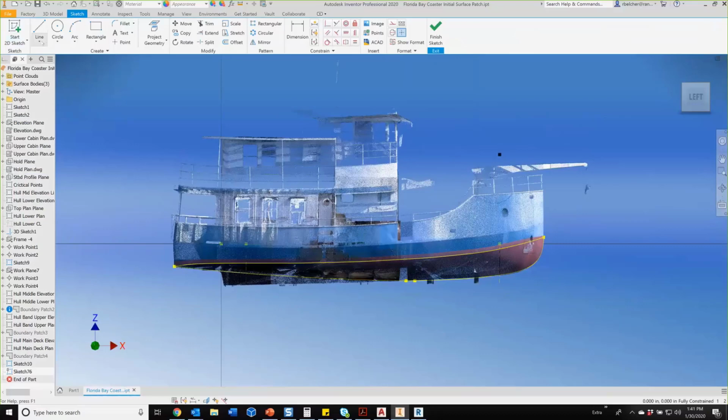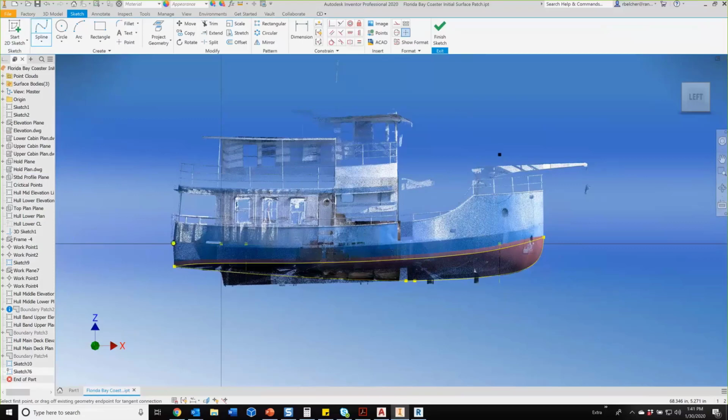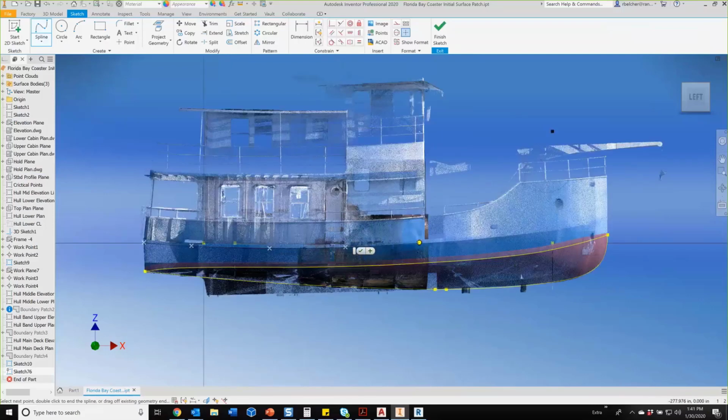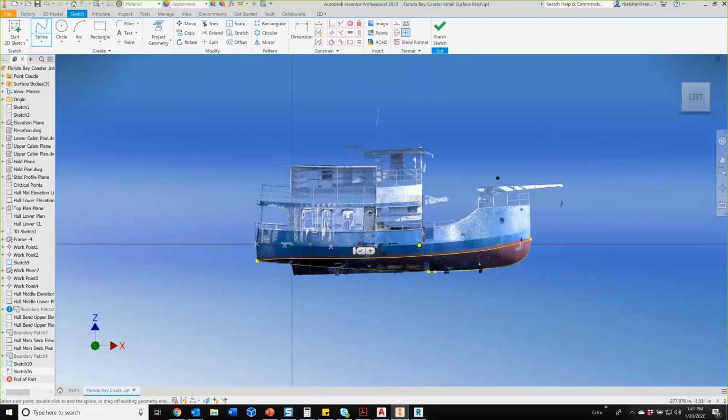Now I'm going to grab a spline. I'm going to use the interpolation spline. That's just the one that I like for this. And you guys forgive me, I'm going to do this really quickly because we don't have a lot of time together today. But if I had plenty of time, I'd have a grid system laid out here, and I'd pay a little bit more attention to exactly where I'm snapping here. But I'm basically tracing this edge.